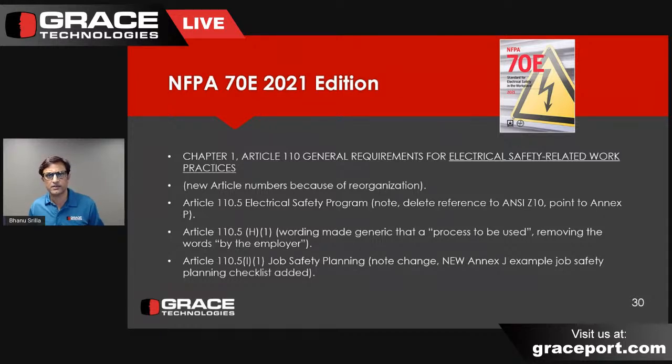Additional retraining we talked about, which requires training and retraining. That language has been changed from just retraining, and how often that is to be done is all spelled out in 110.6. Testing is another, 110.8, which says only qualified persons shall perform tasks such as testing, troubleshooting, and voltage measuring of electrical equipment where an electrical hazard exists. That's one of the changes they added, because that's where you have the qualified person and testing, and you just put two and two together.